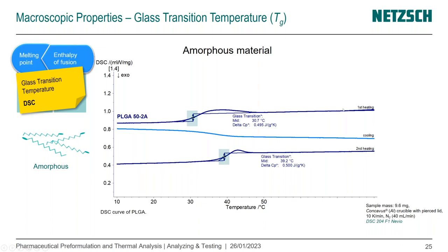So at the first heating here, we do bring all the history of the material, then we cool it down. This cooling is made under certain conditions that are controlled, as we defined before for the DSC method. And at the second heating, we can access a more reliable temperature range for the glass transition. So normally when we work with polymers, with amorphous materials, we take the second heating curve for analysis.